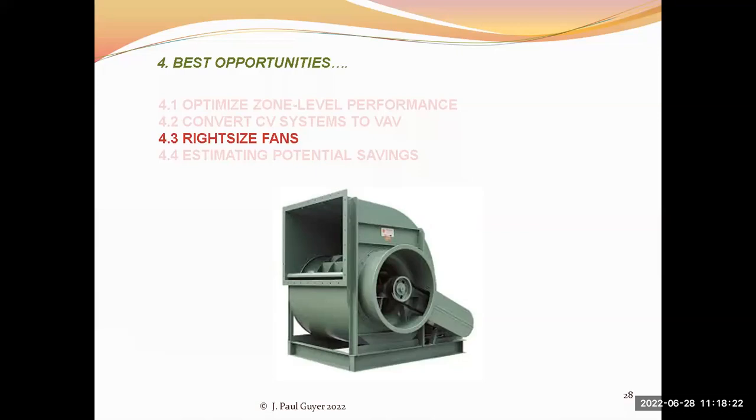And it's best to get this baseline measurement on a hot, humid day if you have a climate where humidity is an issue. Make sure that all fan vanes and dampers and all VAV boxes are fully open, and compare the static pressure reading with the static pressure set point. If the reading is less than the set point and building occupants are comfortable, the set point can be adjusted to the lower static pressure.